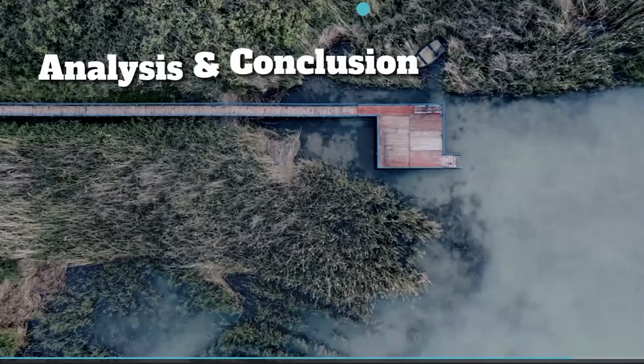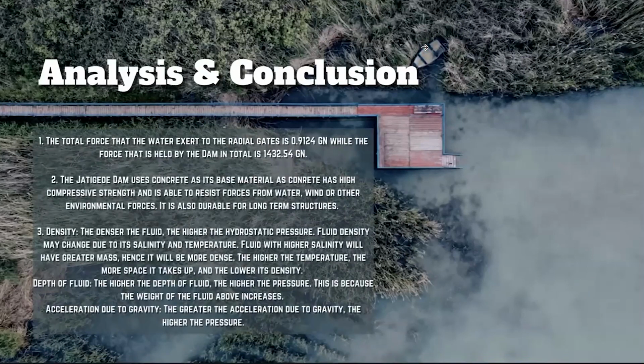From the data that we have obtained, we have made some analysis and conclusions. The first one is that the total force that the water can exert on the radial gates is 0.99124 giganewtons, while the force held by the dam in total is 1432.54 giganewtons. Number two is that the Jatigede Dam uses concrete as its base material for the walls, since concrete has high compressive strength and is able to resist big forces from water, wind, and other environmental forces. And last, it is also durable for long-term structures.